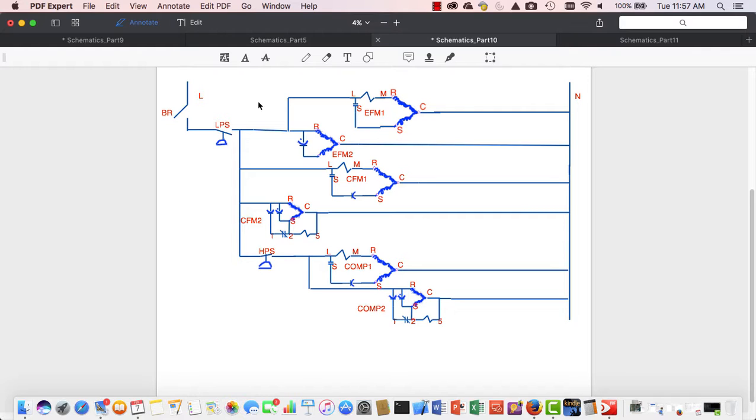So it's going to be about 62 psi of pressure, and you can check that on your pressure temperature charts. So we set the low pressure switch at 62 psi, and that's the cut out. In other words, we turn it off at 62 psi, and we turn it back on at about 70 psi. So we're cycling the system based on the evaporator temperature and the low pressure.